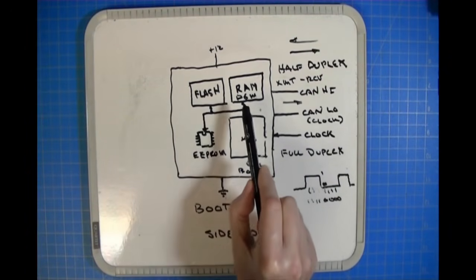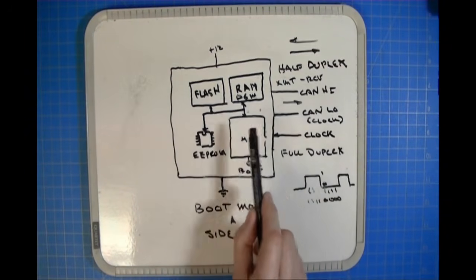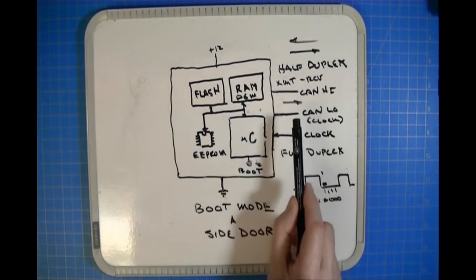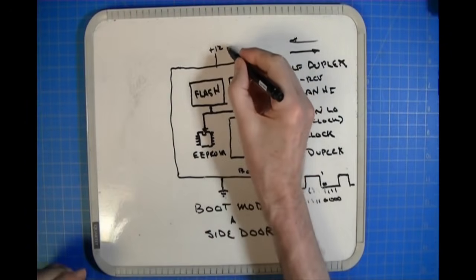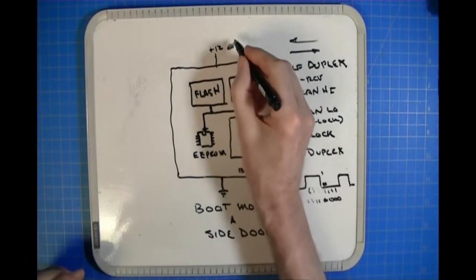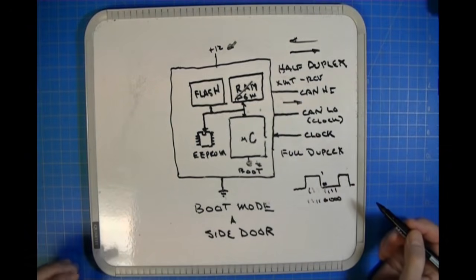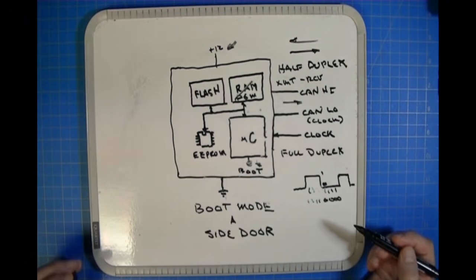Okay, from RAM. Once you've done all of the activities and procedures you want to do, when you're going to read, backup, program, whatever you're going to do, and you turn off your power supply, this goes away. The program disappears, and you are no longer in boot mode. Okay, so unlike BDM, which will always be there when you start, you don't have to do anything.